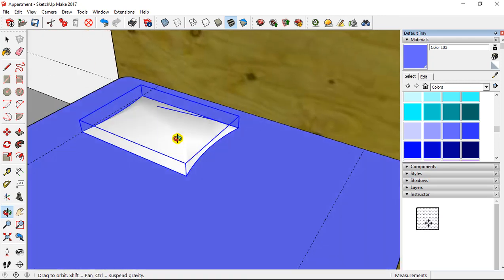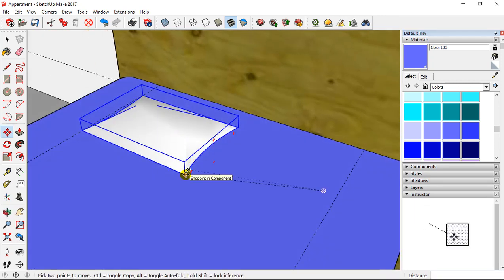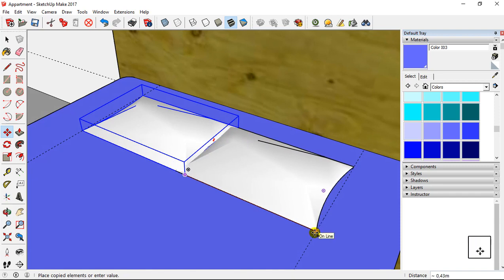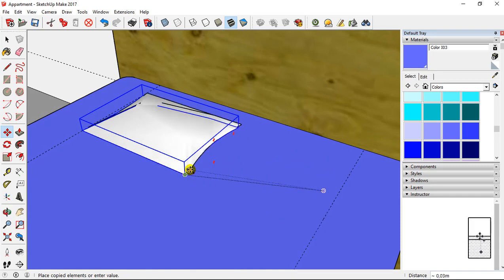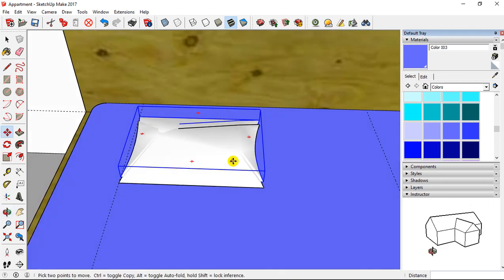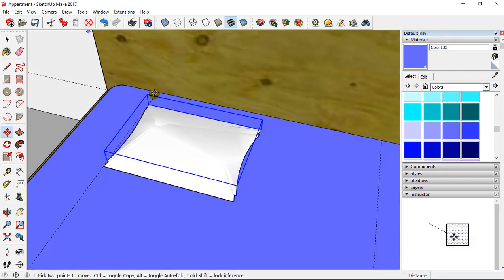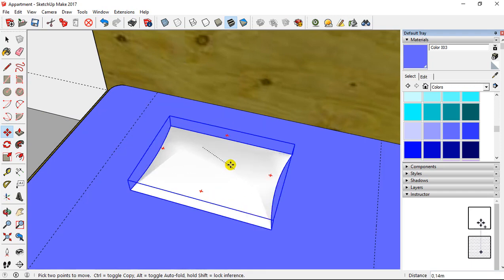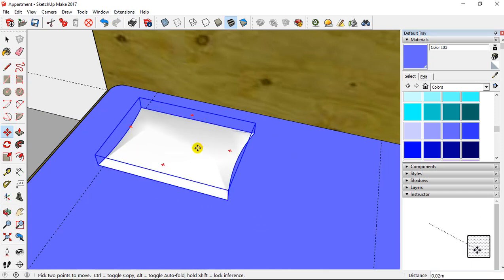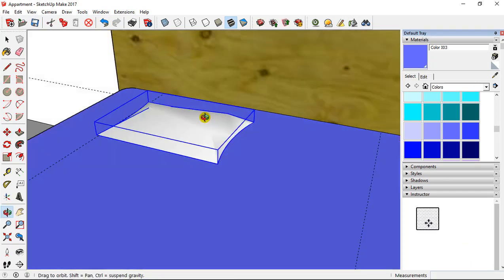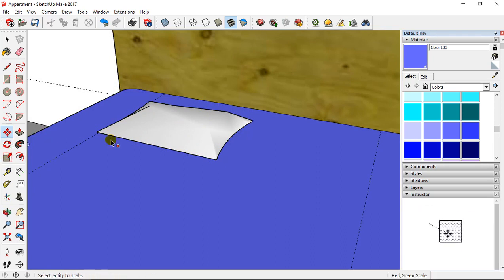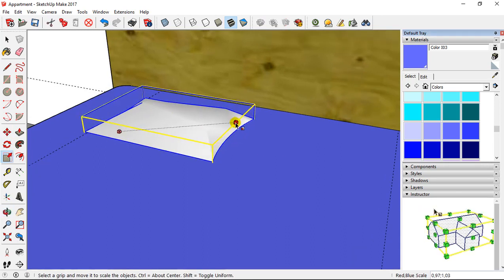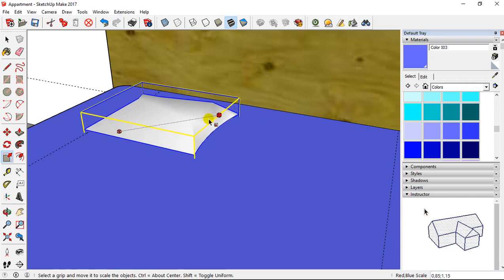Then I'm going to duplicate that, so I take this point, Control, left click, and I can duplicate also. Here you see it's a little big, so the first thing that I'm going to do, it's again to take the Scale Tool. Here I'm going to place this again, to take the Scale Tool, and I'm going to reduce again the pillow, like this.